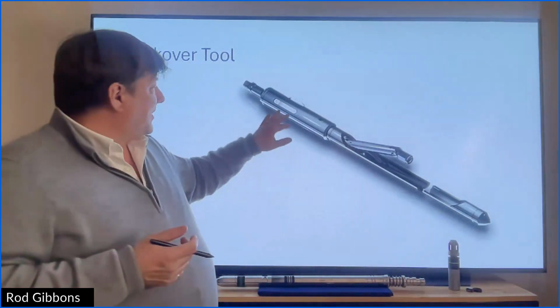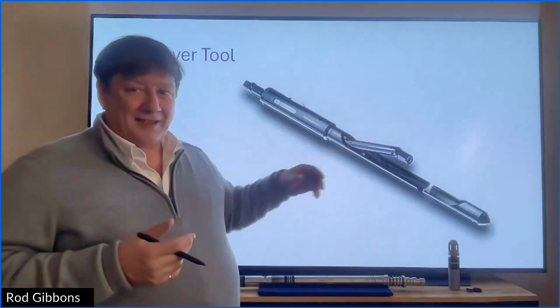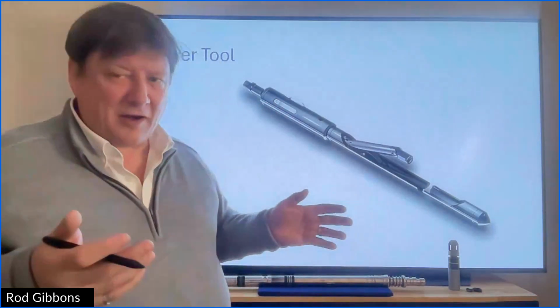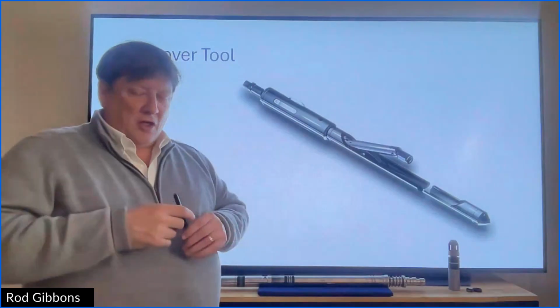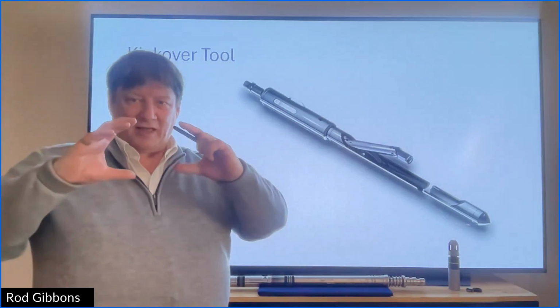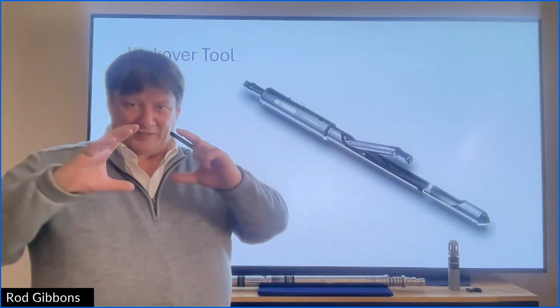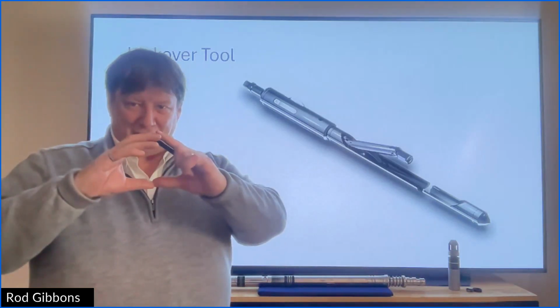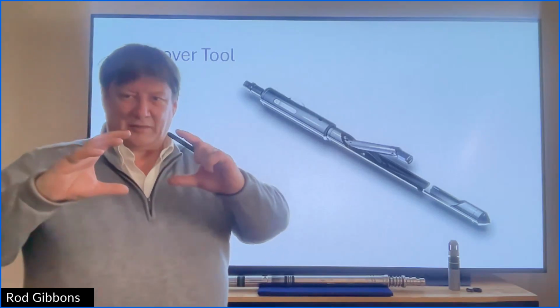And again, a very clever design. If your tubing is this big around, but your gas lift valve side pocket mandrel is this big around, you need to run through the small hole to get to the big hole.